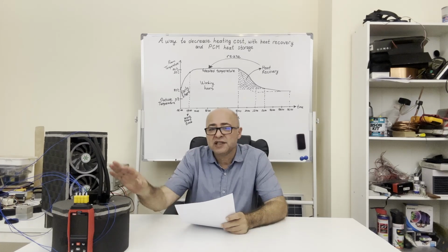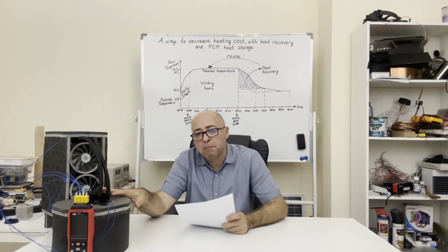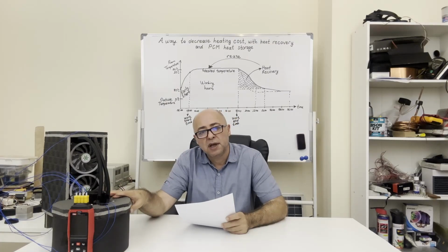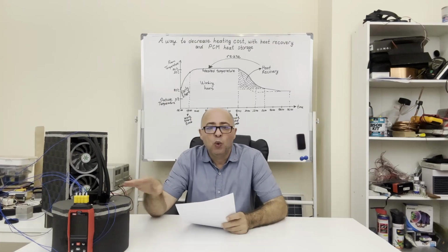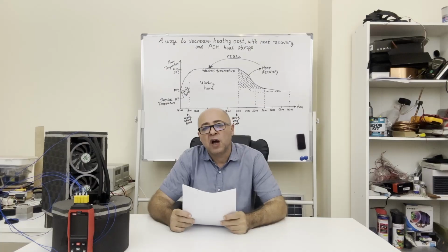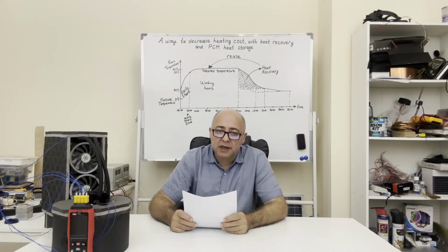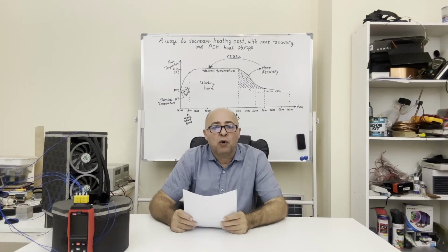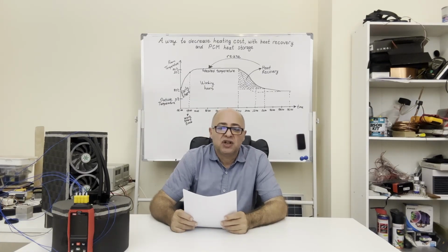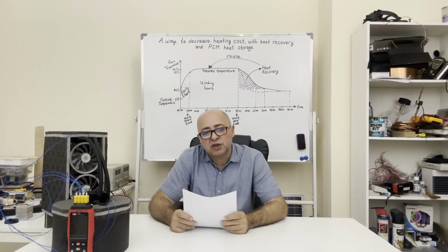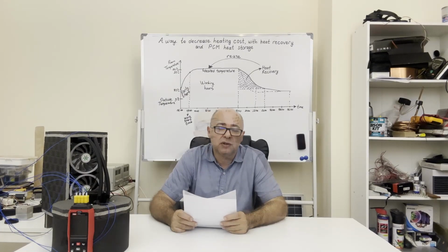I want to show you a small capacity prototype as an example and measure the results. The prototype will have a heating power of 75 watts and a thermoelectric module will be used as a heat pump. I would also like to point out that it will be more efficient if a gas refrigeration cycle system is used instead of the thermoelectric module.